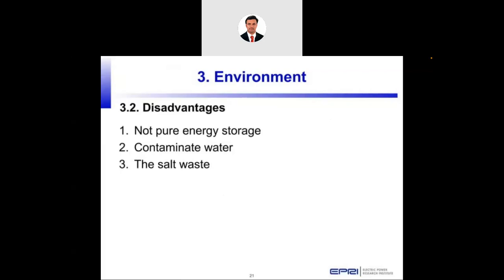But the main disadvantage of this power storage is that it is not a pure energy storage, because whenever we store the compressed air inside the earth crust in depleted natural gas caverns, it sometimes gets contaminated. It comes in contact with contaminated water and different waste. Whenever we use that compressed air and release it into the atmosphere, it causes pollution. That is the main disadvantage.